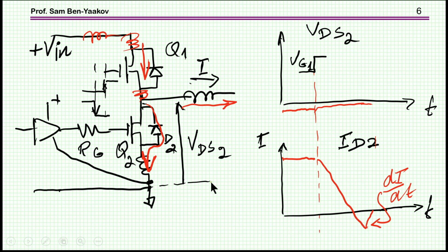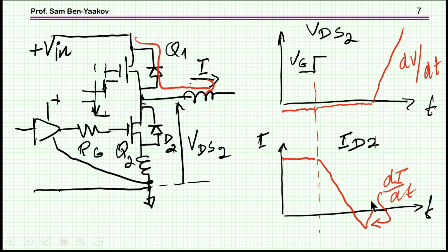During this time, the current is actually in the opposite direction. Okay? And then we have the recovery, and eventually, of course, the diode is not conducting, and all the current is actually passing through from the transistor to the output. Now, during this time of the reverse recovery, first of all, as long as there is a current in the diode, the voltage is approximately the same. As long as there are some charge carriers in the junction, doesn't matter whether it's one way or the other, we have about the same voltage. And then once the reverse recovery is sort of finished, then we start seeing the voltage rise of this transistor due to the charging of the capacitor, and eventually it of course locks to the Vin.